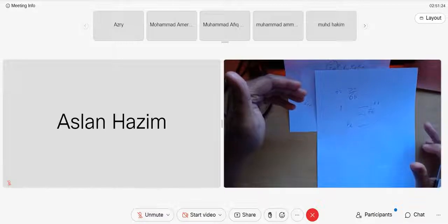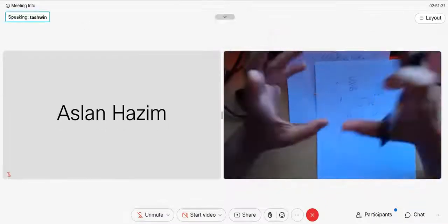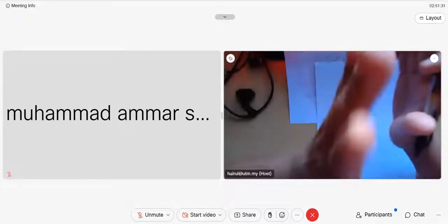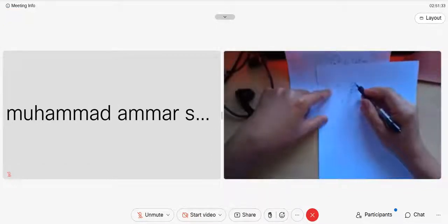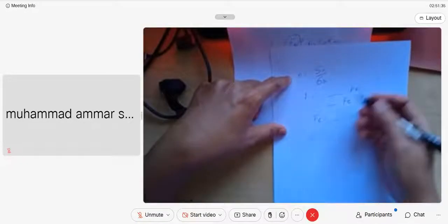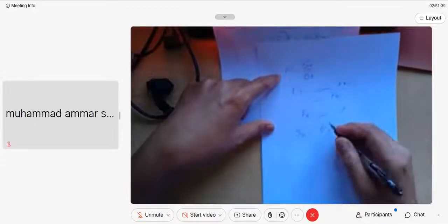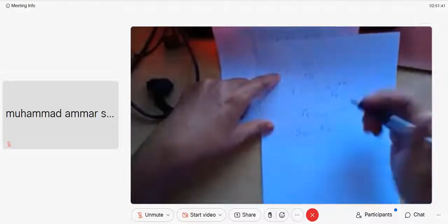Yes, listening. So it means safety factor 1, because we need to calculate the maximum power. So our borderline safety factor is 1. It means your Sn must be equal to sigma bending. From there, because our sigma bending and Sn we already know in ksi, but sigma bending is in terms of Ft, so we get our Ft.